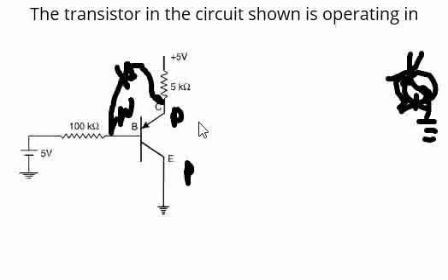Now, to simply answer this, you see here, this is around 5 volts that is provided. This is around 5 volts that is provided. Simply, straight away, by looking at this, you can say that there is no current between the collector and the base terminal, and here itself, we can directly say the transistor is in cutoff region. Now, that's the simplest way of doing.